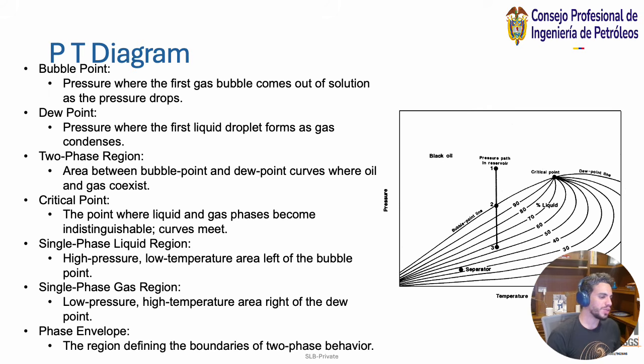Your point in the reservoir is at the highest pressure, because when you drill a reservoir, let's say we'll start at 4,000 psi. Once you drill, through the primary drainage of that reservoir, as you're decreasing the volume of the reservoir, the pressure is decreasing. The pressure will continue to decrease for the life cycle of a reservoir when you're trying to produce, right? So when we're looking at these graphs, we're starting at the top and moving to the bottom. So points 1, 2, 3 kind of explain that.